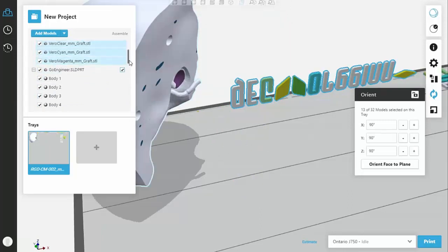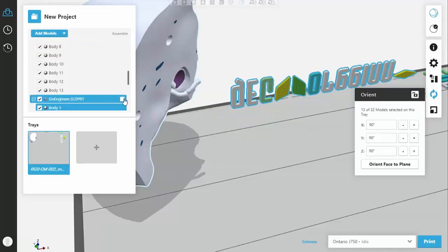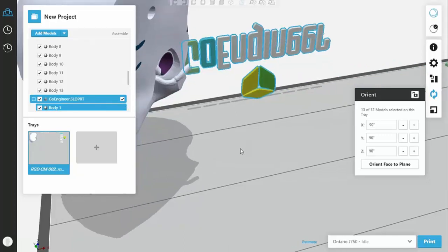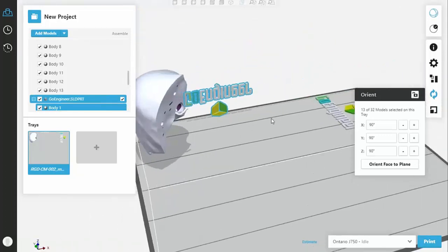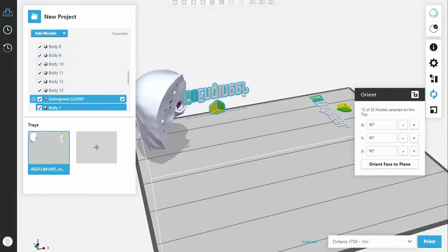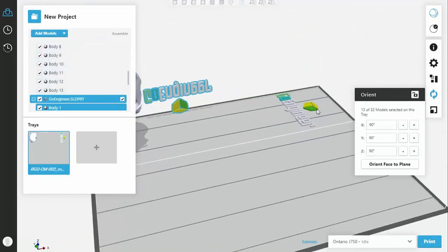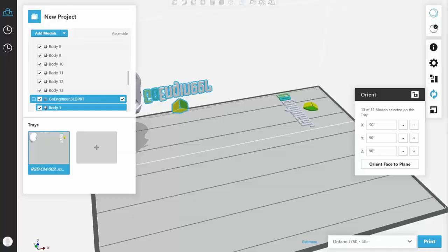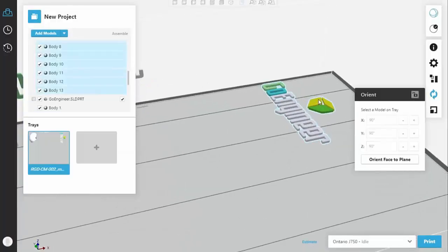I have heard that GrabCAD Print has OBJ kind of on its radar and the ability to accept OBJ files. Separately, there are plugins we can use within SolidWorks to export that wood grain that we saw as a function in the OBJ format. So at some point in the near future, that might be a possibility to include wood grain or carbon fiber or anything like that right out of SolidWorks. But as of right now, we're going to need a Photoshop or something else to do it, which will get demonstrated in the subsequent exercises.